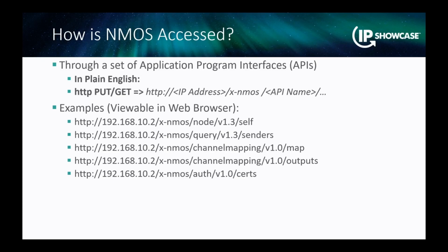You want to change the configuration of the device, you do an HTTP put, which is just like you're clicking on a form, sending in your information back to a website. So it's a very simple protocol. It's not something super complex. So controllers can get to it, web browsers can get to it. You can do it from the command line. There's a little command line program called curl that allows you to send information to NMOS devices. So very simple. It seems complicated, but there's really not much to it under the covers.